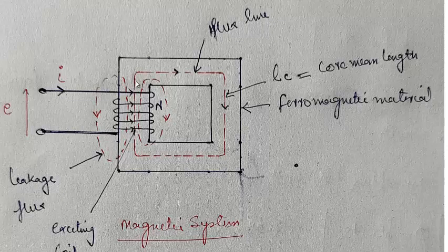So the reluctance of the iron, or magnetic material, is less as compared to the reluctance of the air. So the flux will try to mostly flow through this iron path or magnetic material path, as I have shown you, and some flux may be flowing through the air.